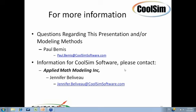Well, yeah, it depends, as it turns out. The inlet temperature that we see people leaning towards the most, and Liz, tell me if you feel anything differently here, is about 80 degrees. The specifications for inlet temp have been rising, and the new specifications that have just been put in place by ASHRAE are, in fact, quite high, above 90. But most customers are happy with 80.6 on the inlet.